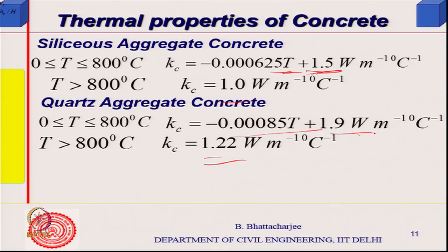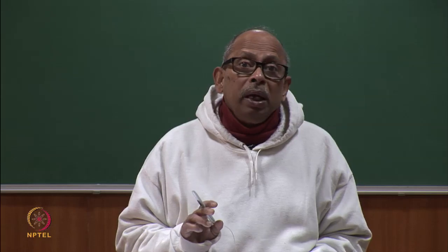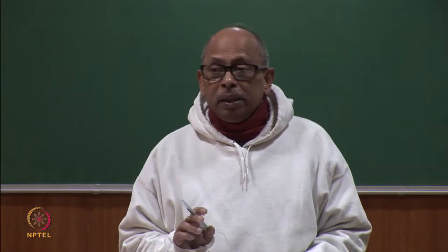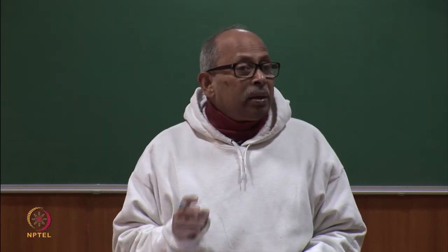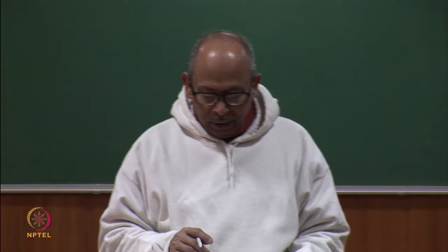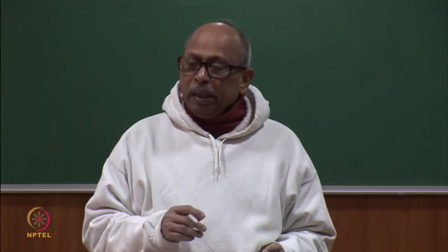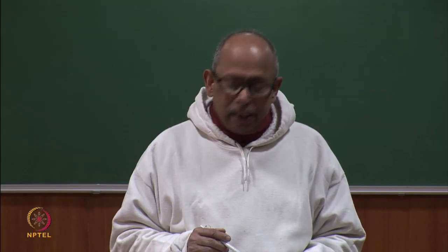Quartz has got higher thermal conductivity amongst all the inorganic materials. Quartz has got the highest thermal conductivity. Pure quartz is of the order of around 10, steel is 50, but the aggregate would be quartzite with a lot of impurities and things like that. So, from the original quartz rock, if you have some aggregates, they will have relatively higher thermal conductivity.